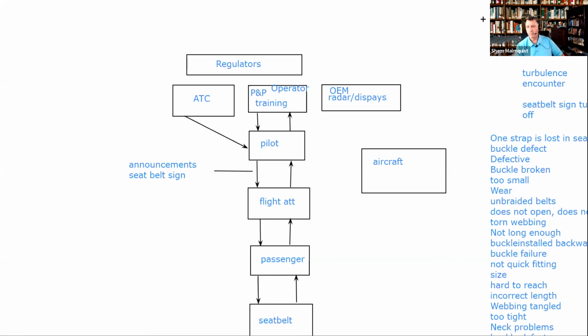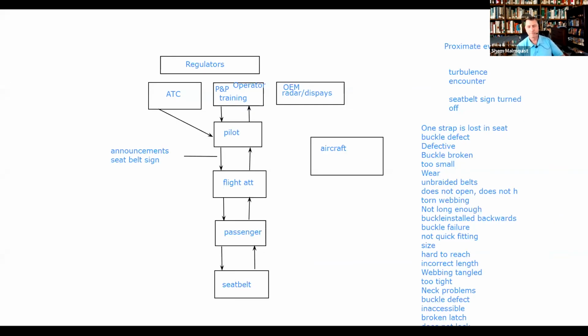Yeah, conflict with TCAS could do it. Not being aware of the weather is certainly an issue. In a lot of the world, the U.S. controllers try to steer aircraft around weather. That's not true in most of the world, or varying degrees. So one of the areas that's putting pressure on the pilot to make a decision could be air traffic control.